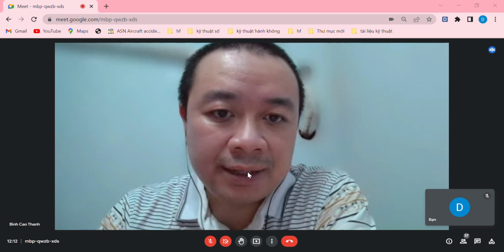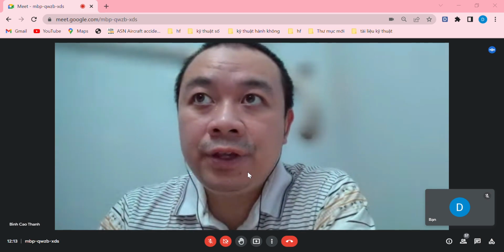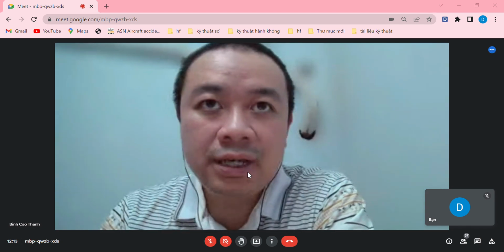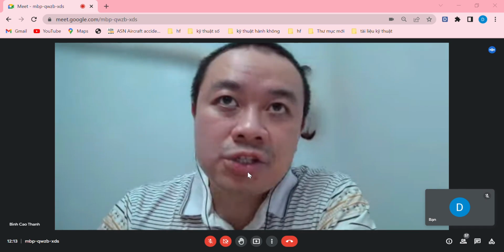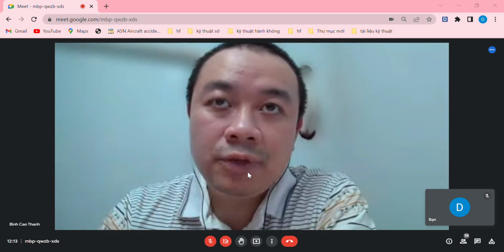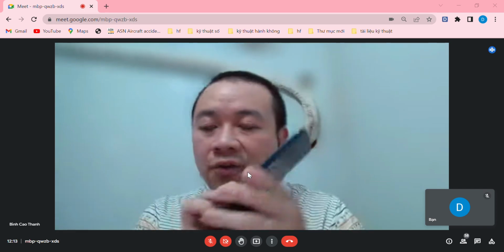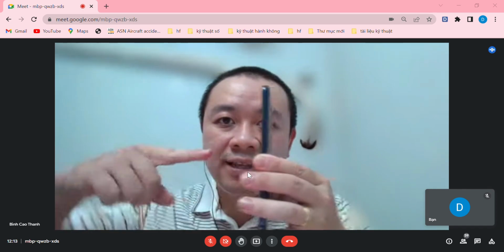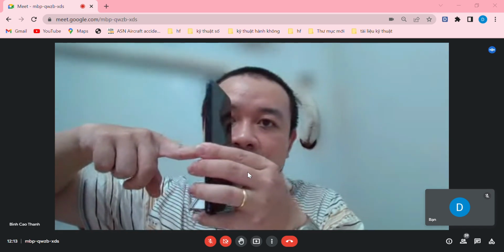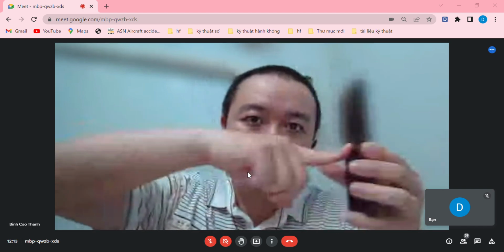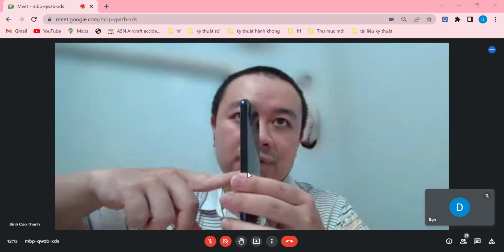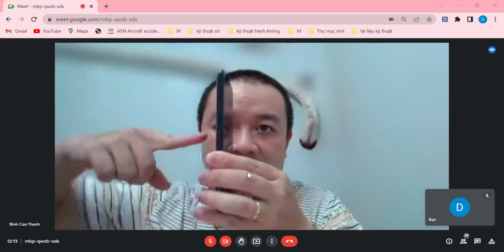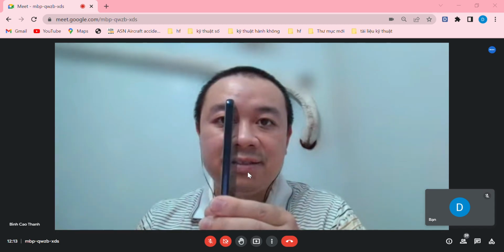So please remember that. And once you have the discrete time model, then you can define some kind of load, external load applied to the part. Constraint is meant to fix the model. For example, if you apply the load to this cell phone and you do not fix the phone in a certain position, then when you apply the load, it will push the cell phone so that it moves. And if you constrain, it means that you fix the position, you apply the load, and then this is the case.